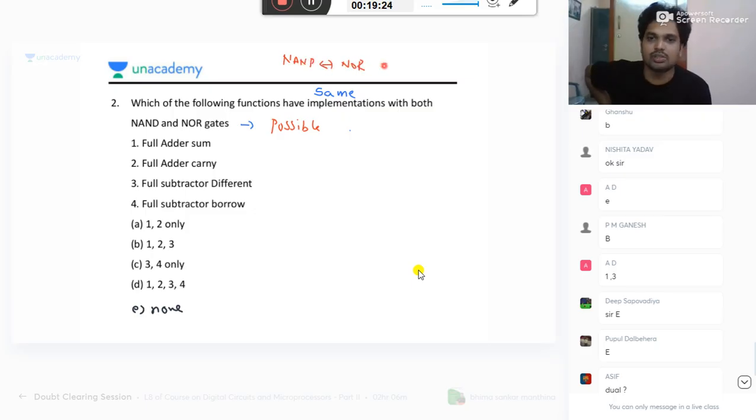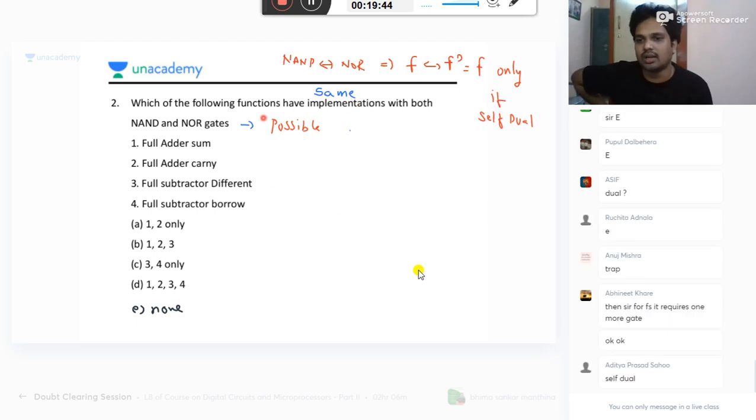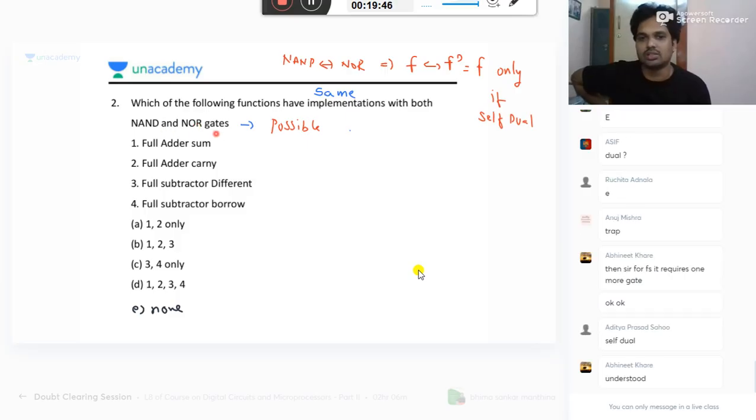Next, switch tail D. That is D to Q bar. So now you take one line, and switch tail means what? If you say ring, Q should be connected back. If I say switch tail, who should be connected back? Q bar should be connected. Switch tail means Johnson. Switched tail or twisted tail, Johnson only.